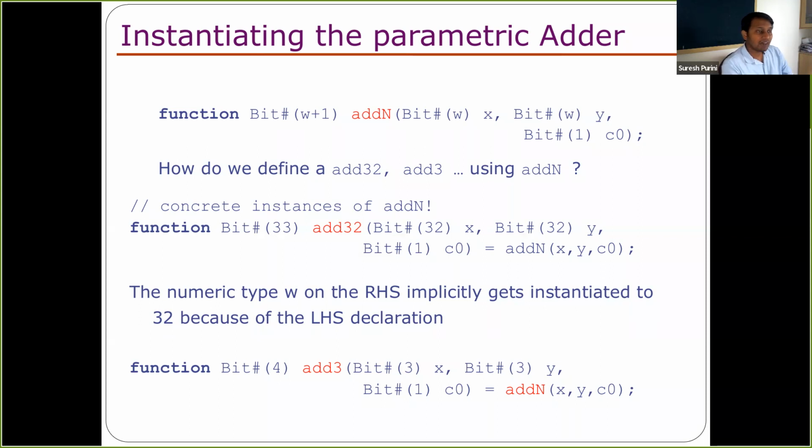So you can write a generic convolution computation module where height and width are parameters, and the filter dimension is also a parameter. You write parametric code, and depending upon what image, what resolution, and what filter you would like to apply, you can instantiate a specific module.